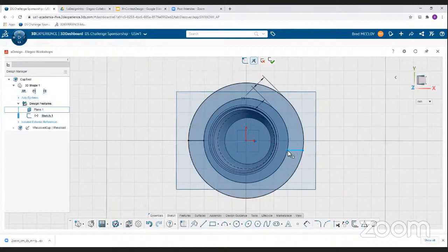So if that happens, what we can do is say, okay, we want this point and the one I'm packaging, you don't have to hold down Control. So select the origin and this line, and we can say we want those to be horizontal with respect to each other. There, now it's turned black and it's horizontal. But we've got a full circle. We only want a semicircle.